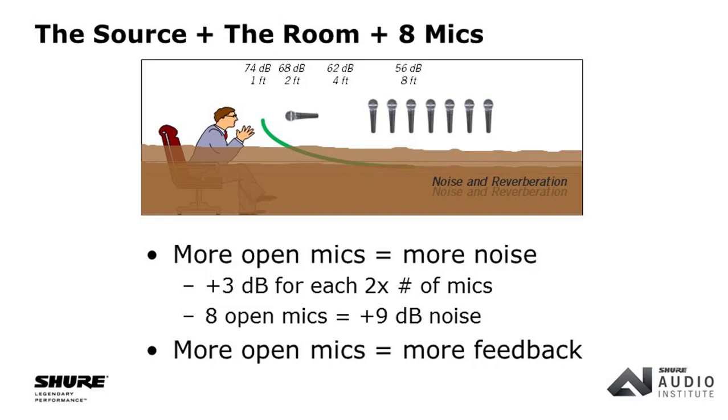And if you're running a sound system at the same time, you'll be getting closer and closer to the point of feedback. So if we learn one thing today, it's that you've got to control the number of open microphones, whether it's by people pushing a button when they want to talk or having a device like an automatic mixer do that for you.